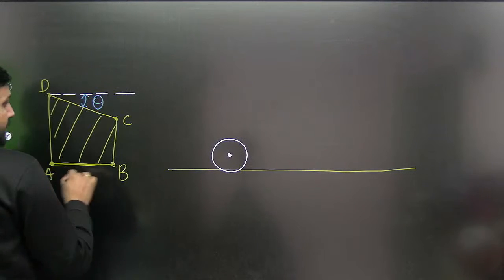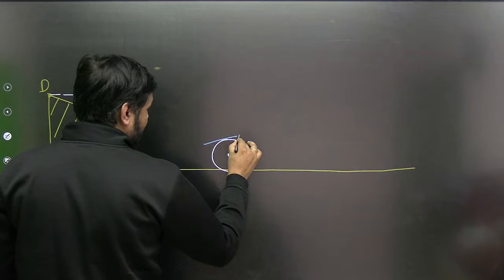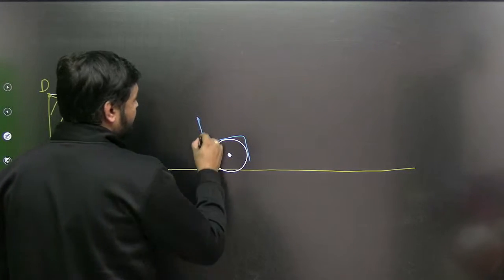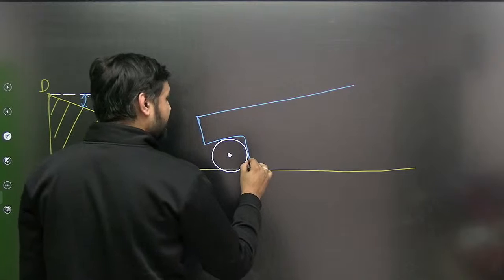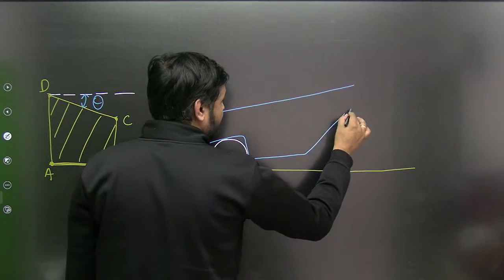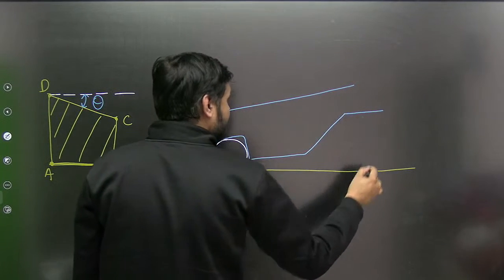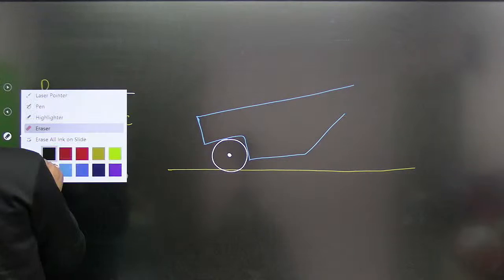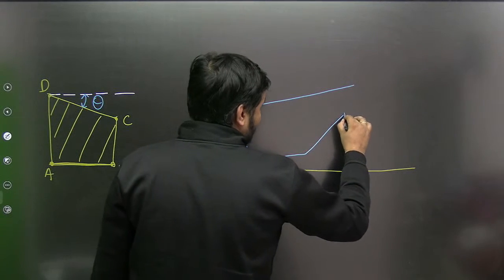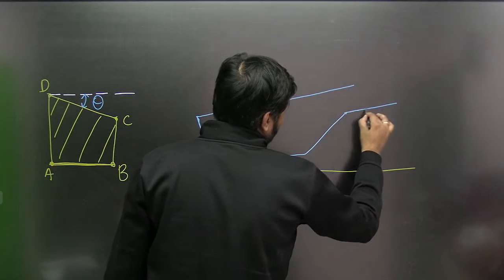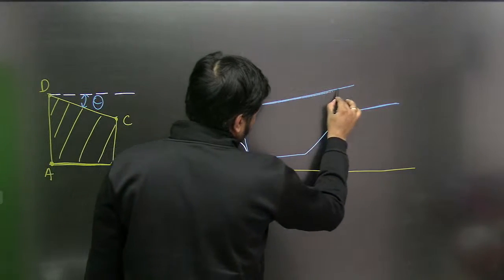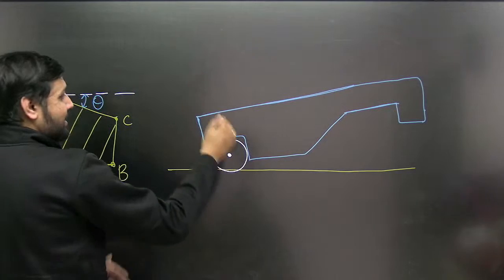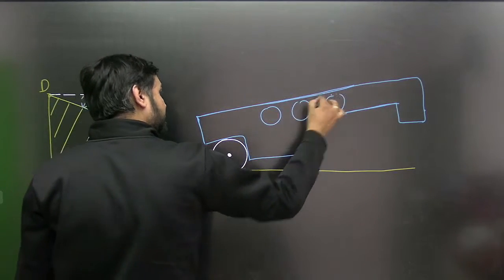This sine bar is mounted there onto the roller, but my dear, what we are going to do is pile up a certain number of slip gauges on the other end of this sine bar, so that the sine bar starts getting some tilt into the upward direction.